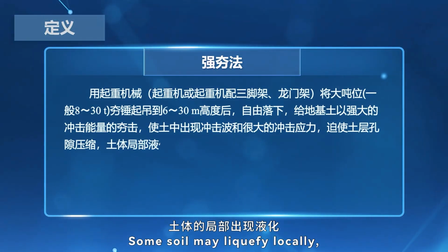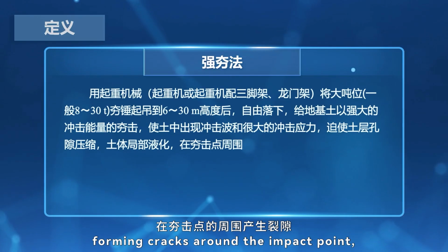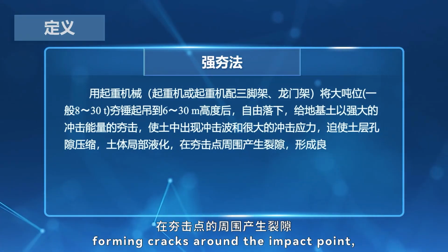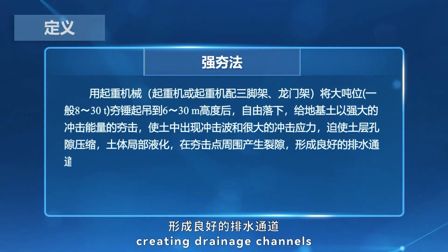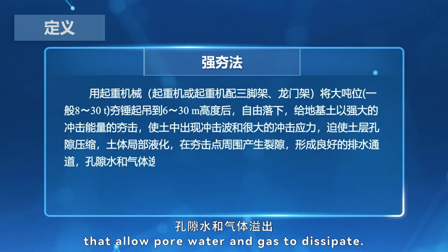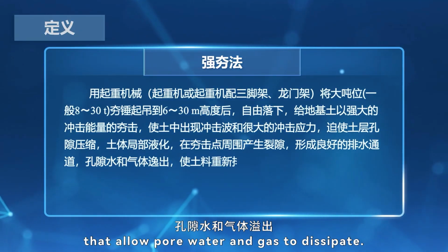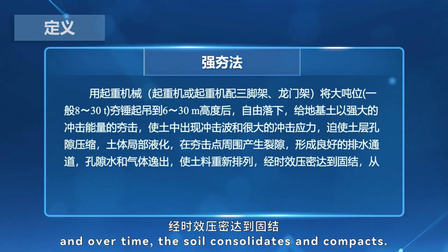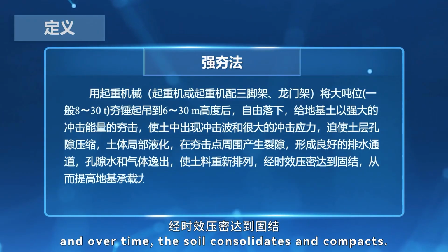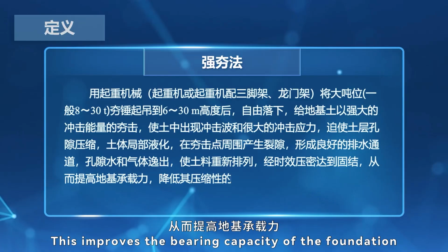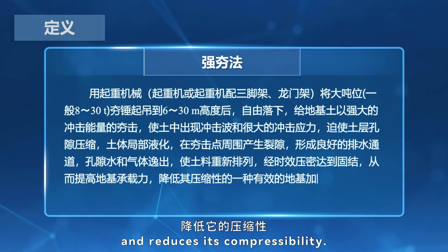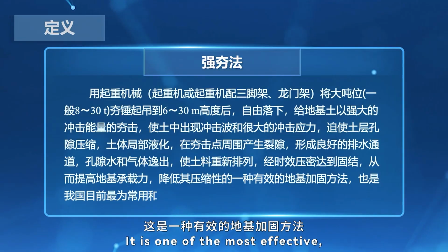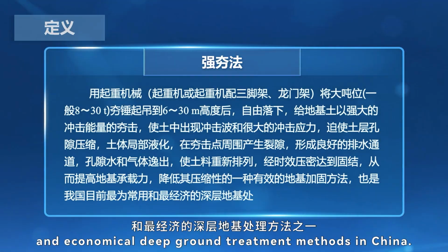Some soil may liquefy locally, forming cracks around the impact point, creating drainage channels that allow pore water and gas to dissipate. Soil particles rearrange, and over time, the soil consolidates and compacts. This improves the bearing capacity of the foundation and reduces its compressibility. It is one of the most effective, widely used, and economical deep ground treatment methods in China.